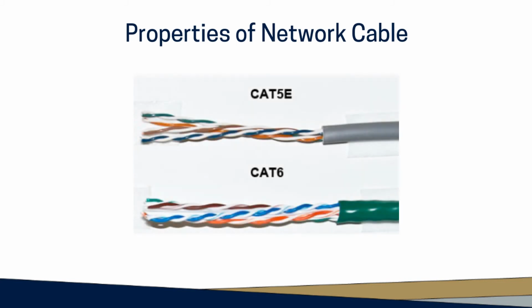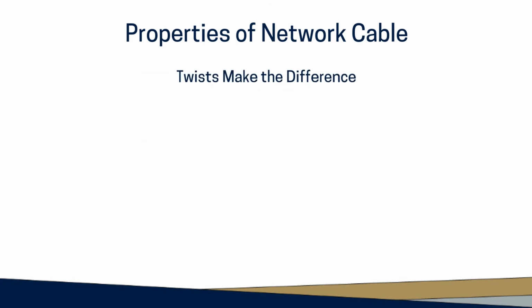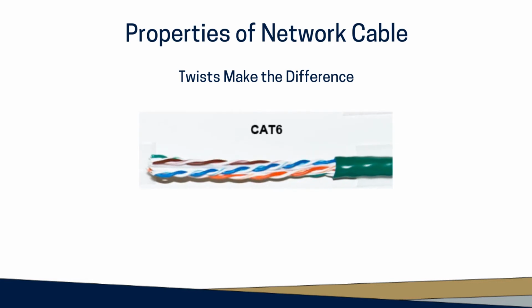When you remove the outer sheath of a Cat6 cable, you will see 4 pairs of twisted, color-coded wires. The number of twists per unit of distance is a major determining factor of the classification of a network cable. Category 6 cables have roughly 5 twists per inch. It's very interesting to note that each pair has a slightly different number of twists per inch. There are electrical noise reasons for this difference. There's nothing wrong with the cable.